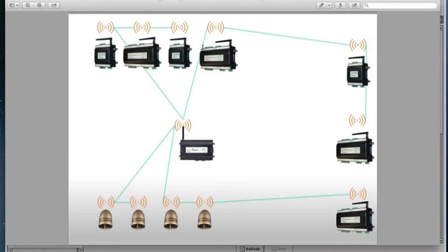In building applications, we've seen projects where the JACE from the bottom floor is communicated to air handling units through 2.5 floors of concrete and steel directly to the JACE. In those type of projects, depending upon the link quality, is where you may want to adjust your min beacon LQI to force it to have a stronger signal. But the power to penetrate through walls and floors has been very, very positive.